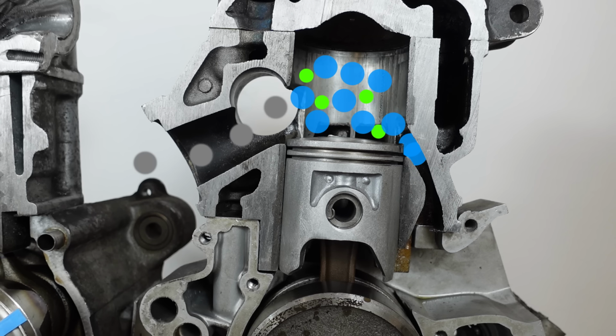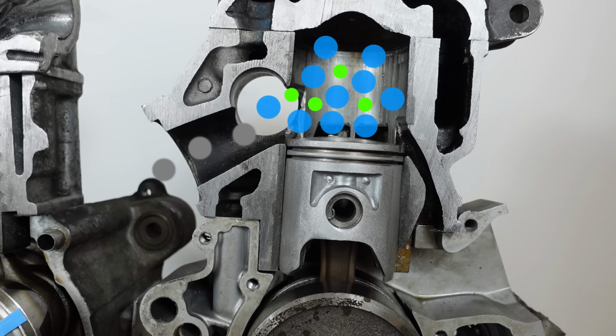But as you can see, our exhaust port is still open. It's not blocked off by the piston, which means that the air-fuel mixture not only pushes the remaining exhaust gas out the cylinder, the air-fuel mixture itself is also free to exit the cylinder through the exhaust port.